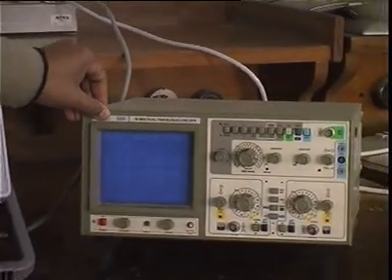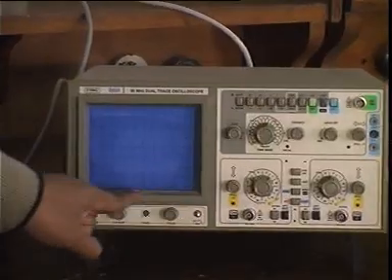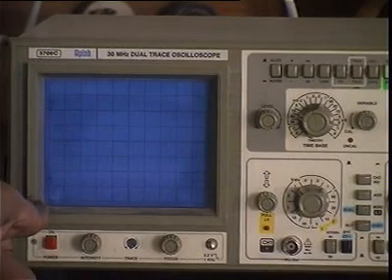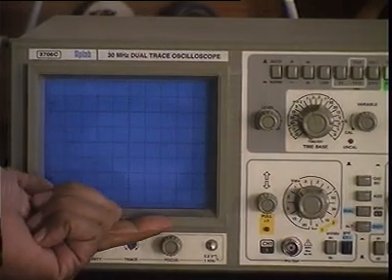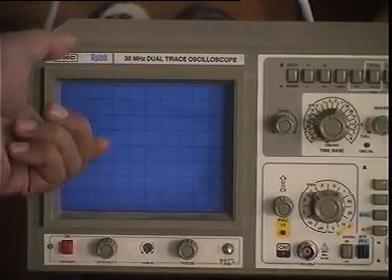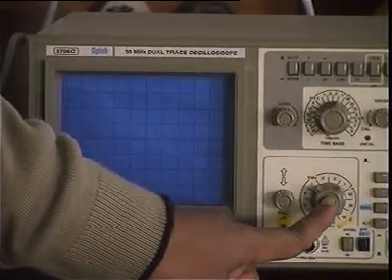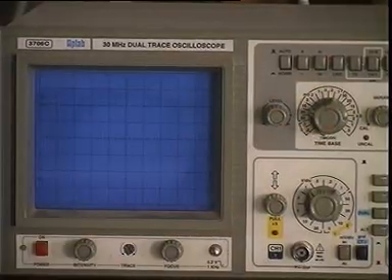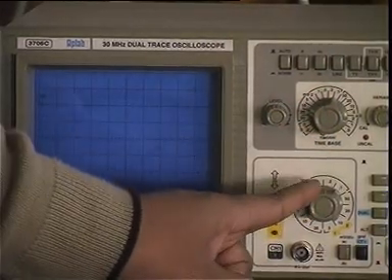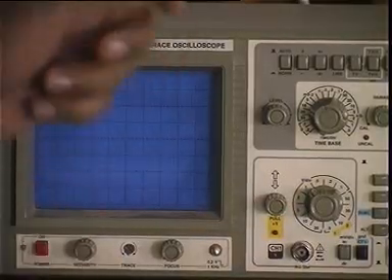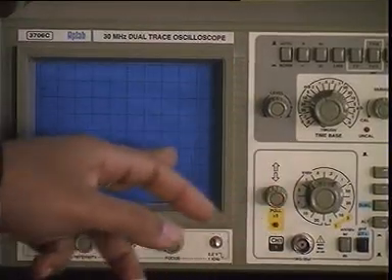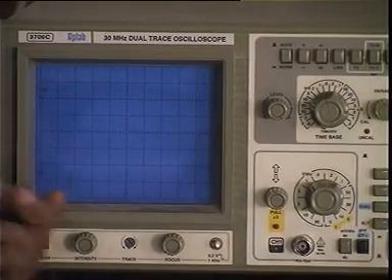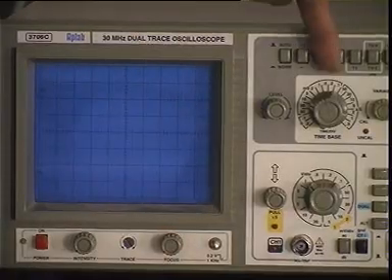Now on the front screen, as I said, the x-axis is the time axis. The vertical axis is the amplitude or voltage axis. I can scale these axes, the horizontal axis as well as the vertical axis, by changing these settings. The vertical axis can be changed by this switch, the horizontal axis can be changed by this switch. Now this switch on top is marked volts per division. That is, looking at the number of divisions here, I can change the number of volts, and so change the scale of the vertical axis. I can likewise change the scale of the horizontal axis using this knob.